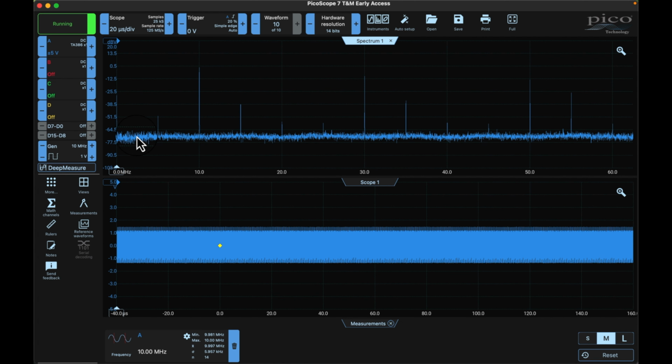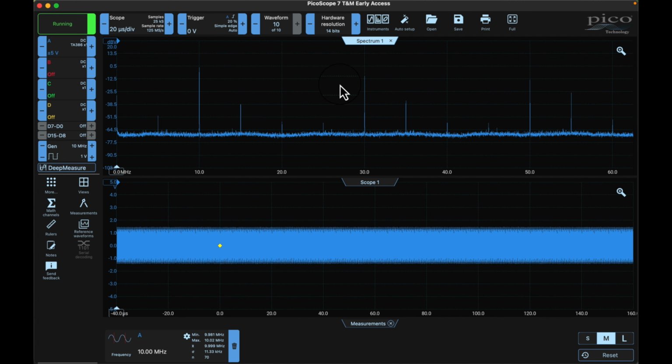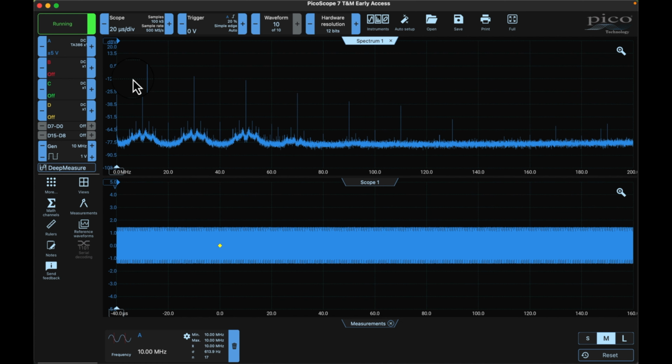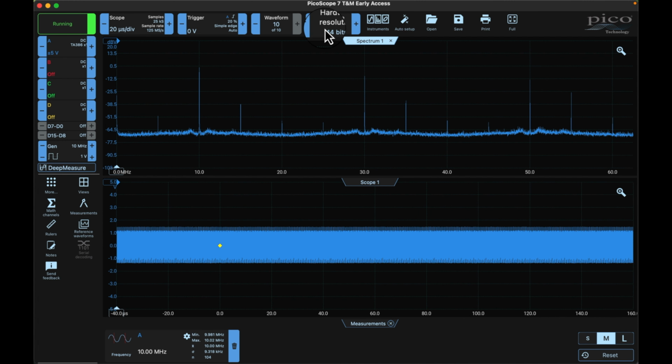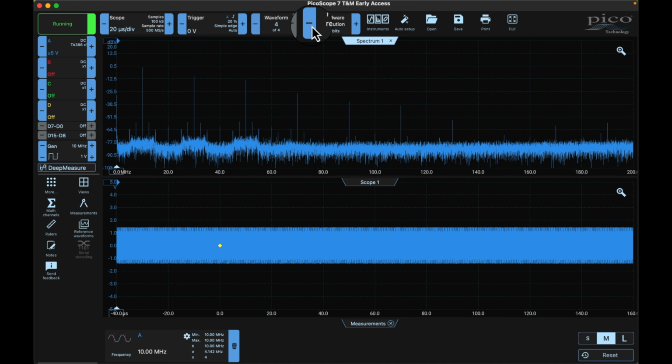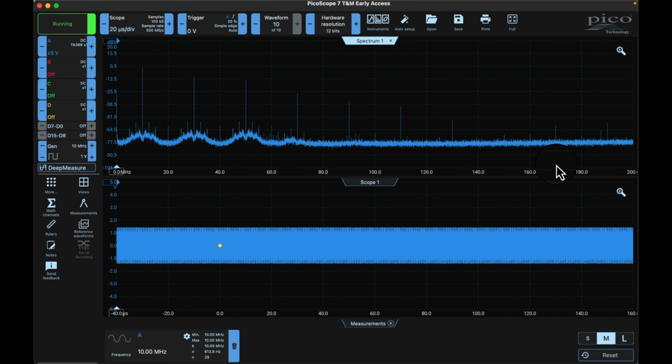So eventually there's a point of diminishing returns. You might be noticing maybe I'm losing a little bit of my actual frequency resolution here, so maybe that's not working as great. Yeah, see that 10 meg? It pretty much disappeared when I did that, right? Look at that. Well, actually what it did is it shifted it over. See over here, we're at 60 megahertz, so I'm losing my frequency resolution. And right there, I still got my 200K.